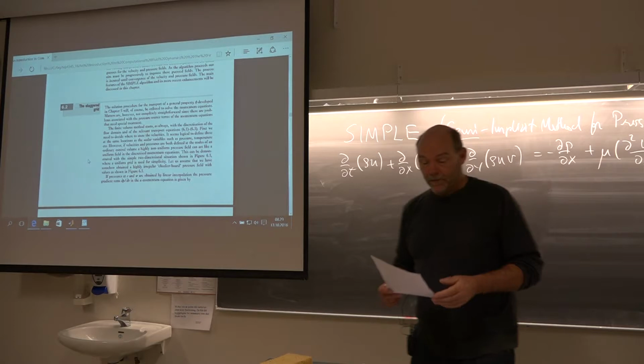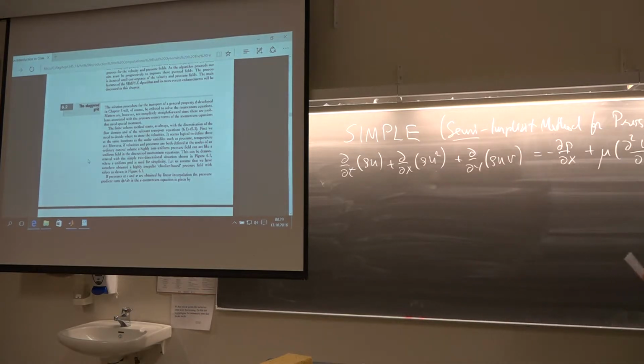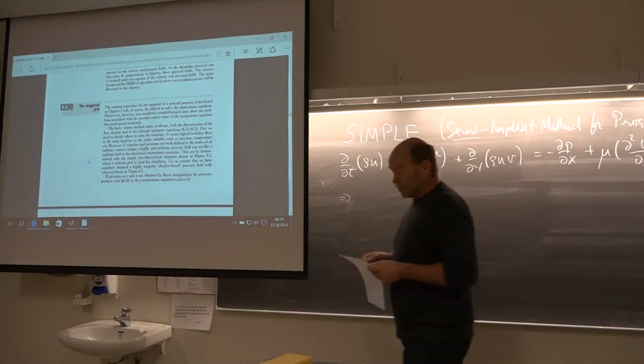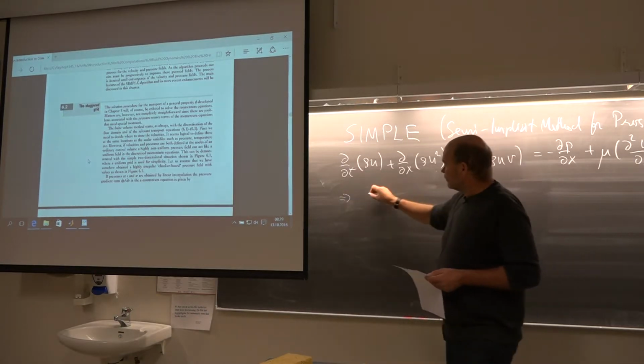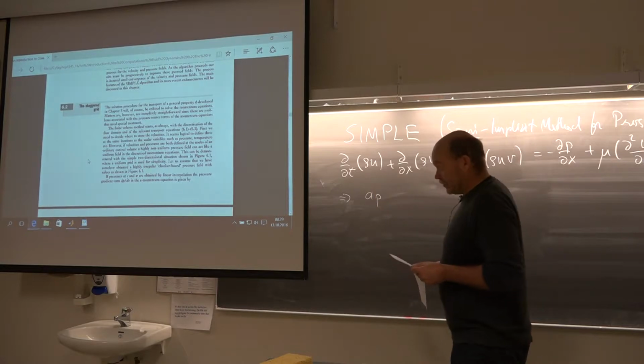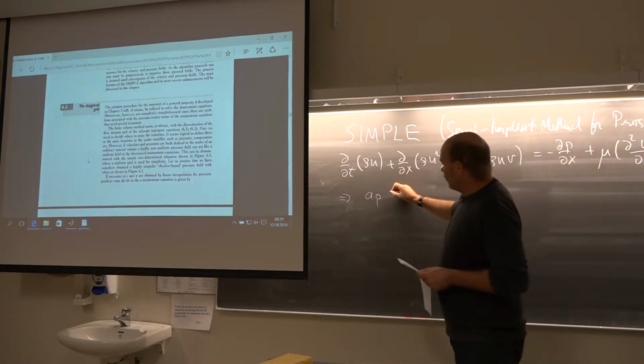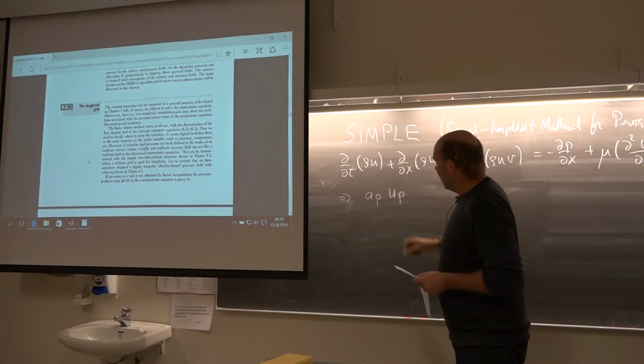Now from this equation system, the differential, or actually what we are doing now is the integral version of this one, integrate both in space and in time. Either way, you will end up with an algebraic equation system going like this. You have the center point coefficient, AP, and your unknown, now a velocity.